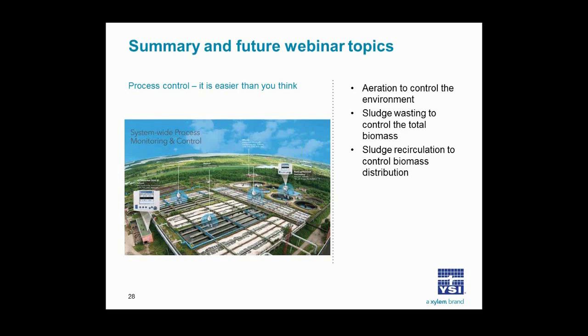with denitrification, really there's two conditions. One is you could either be nitrate limited, in which case there's not enough nitrate, or carbon limited, in which case there's not enough carbon. And so measuring that nitrate tells you which condition you're under. If you're nitrate limited, for instance, in the anoxic zone, the response is to increase the recirculation rate. On the other hand, if you're carbon limited, increasing the recirculation rate may not improve performance. So you need to know what that nitrate concentration is.